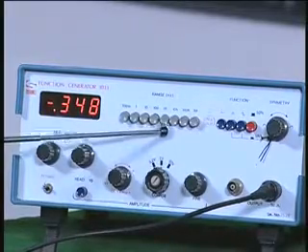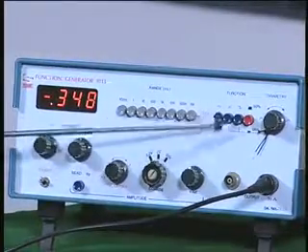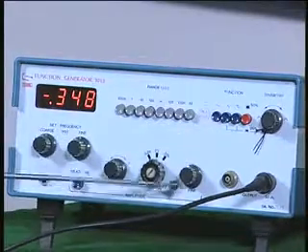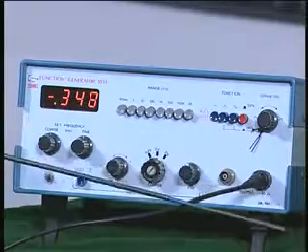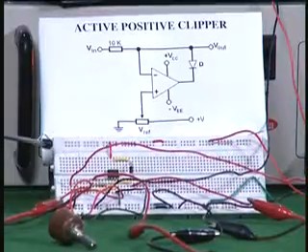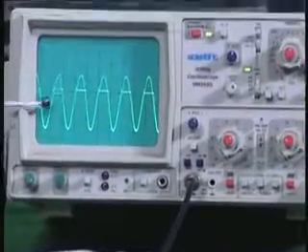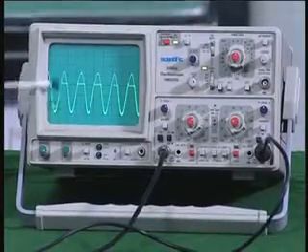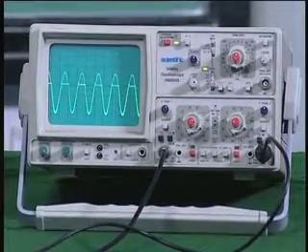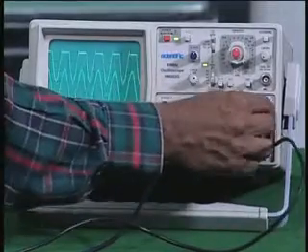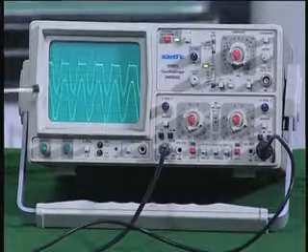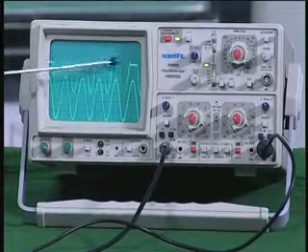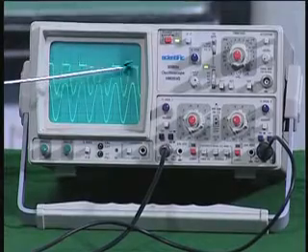So you have again at 1 kilohertz a sinusoidal wave, and the amplitude is adjusted using these two knobs, and this is given as the input to the board, and the output is connected to an oscilloscope. As a matter of fact, in the oscilloscope both the input and the output are shown simultaneously. If I slightly move, you can see the two signals. You can see that the bottom one is the input signal, the top one is the clipped signal. You can see the clipping there.